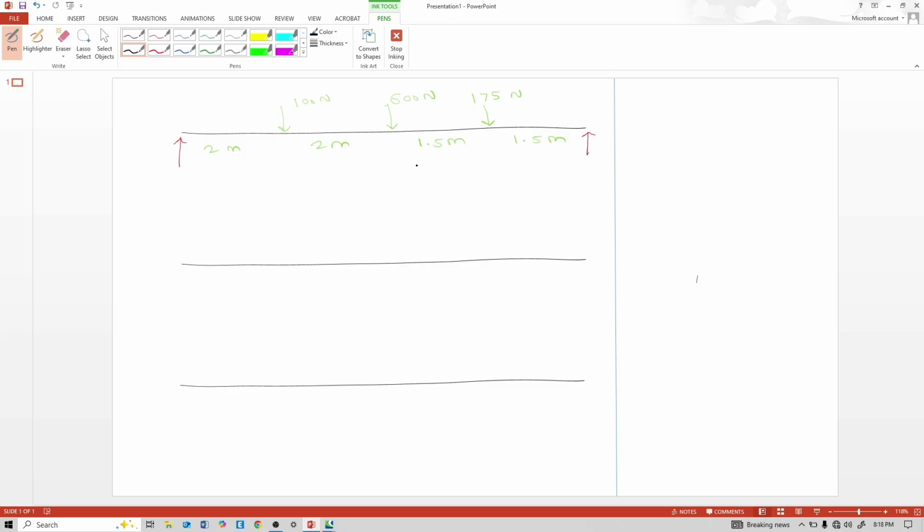These loads are downward loads, and for every action there is an equal and opposite reaction. So these reactions, the red color reactions, come upward. By that judgment, we will consider here that shear force is upward. This red color at point A is upward, so the reaction is upward, which means shear is also upward.